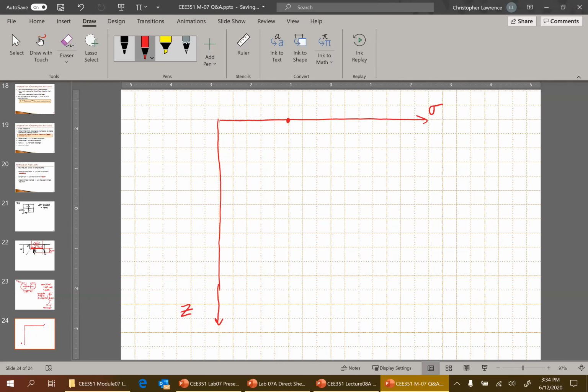But then, actually, it says sigma Z as a function of depth, with the same applied stress at the surface. So it doesn't really matter what Q is. For any Q, if the square and the strip both have the same Q, what if you just plot influence factor? Because you can factor out the Q. They're both the same Q. The only difference would be influence, right?